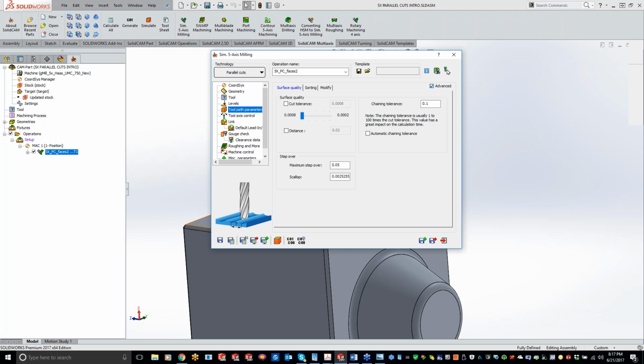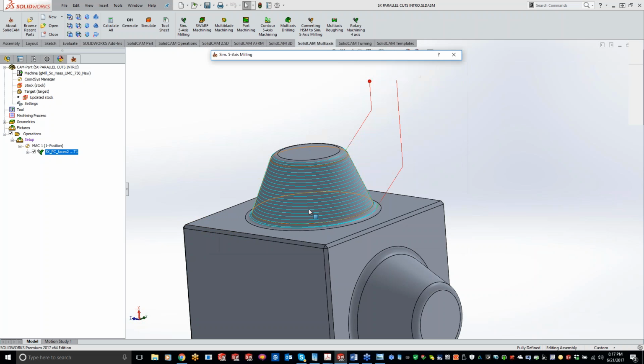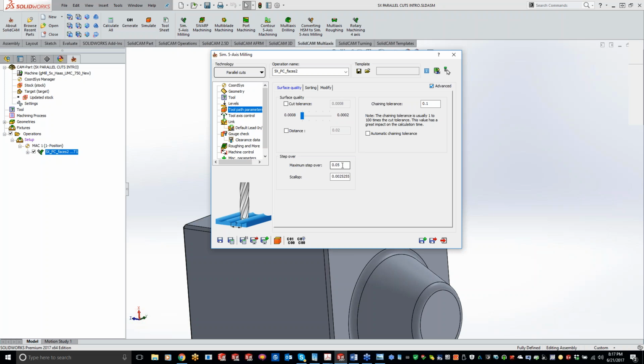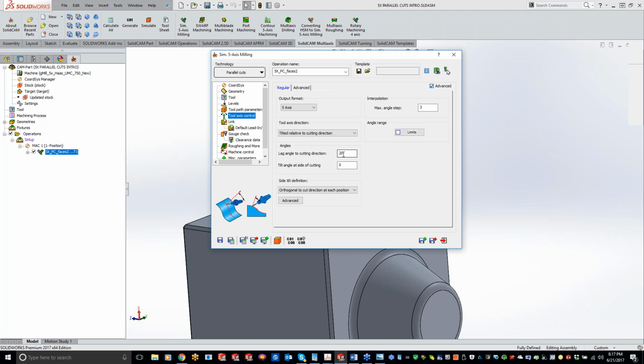It's a lot easier to look at a toolpath when it's spaced out and see what's going on versus if we have a solid green line right here. So let that be the last thing, and now I can crank that down to a 10 thou step over and really get a really nice finish on there. But like I said, it's more user preference on laying that over.